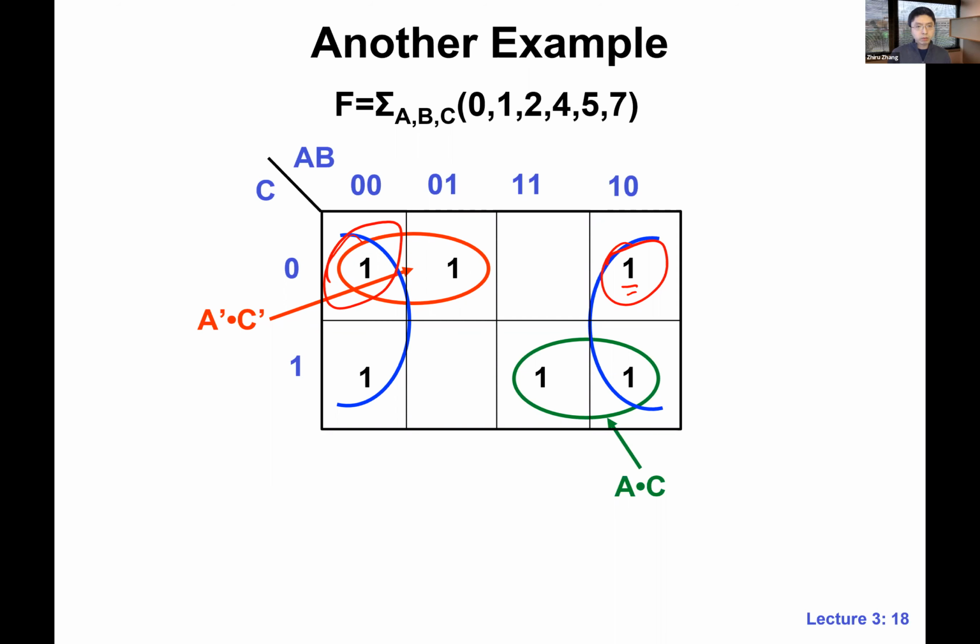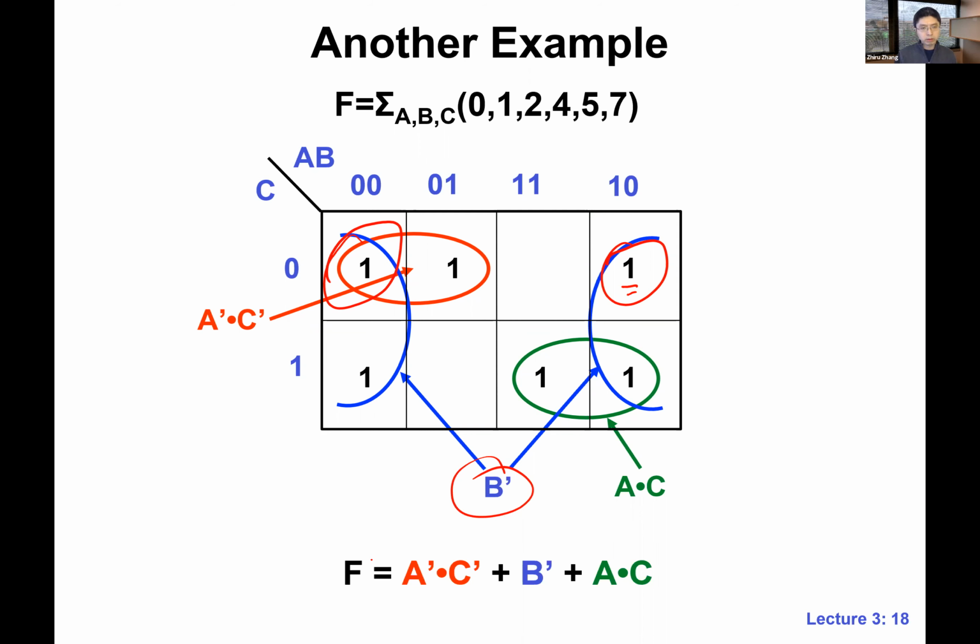If there are no more questions, so this is basically B prime. When we combine 4 things, we knock out 2 literals, and we end up with 1 literal. And we can just order them together, so this is the final form.